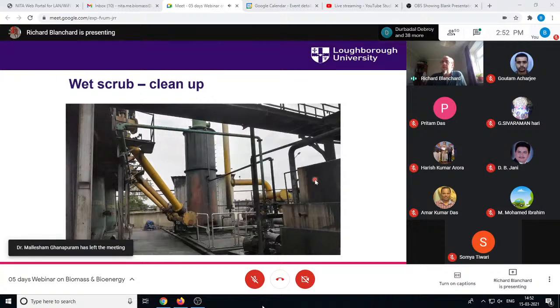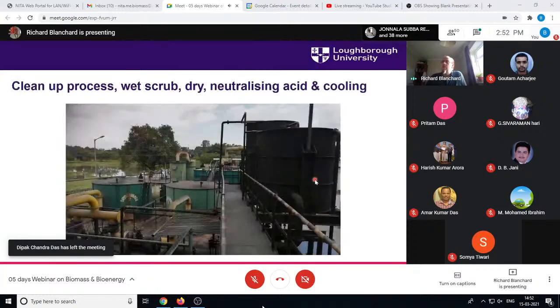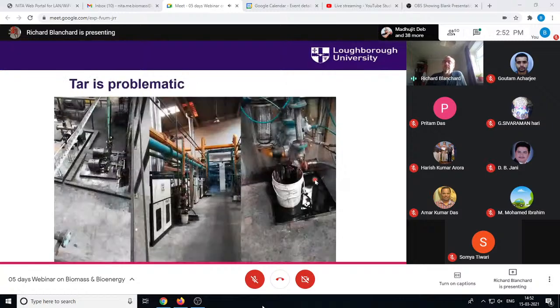And that is there's a lot required. So you have to clean up gas to remove particulates and tar. So you've got a whole range of scrubbing and cleaning processes required here, to make sure the gas is going to go into the factory clean for combustion and baking biscuits. One of the challenges with gasification is tar, and it is the $1 million question: if we solve this, the root of producing tar in the first place, this would make gasification much more attractive.